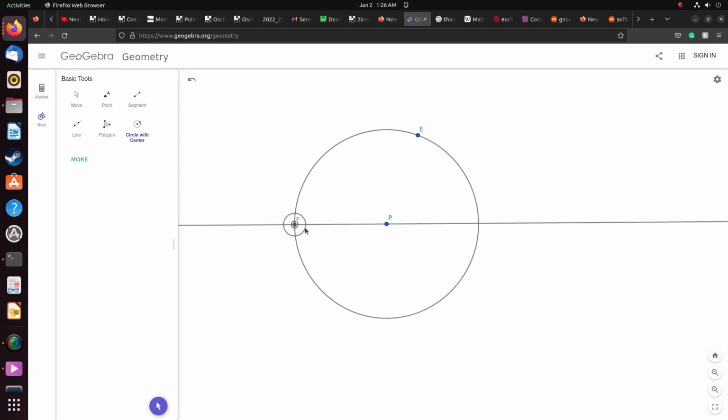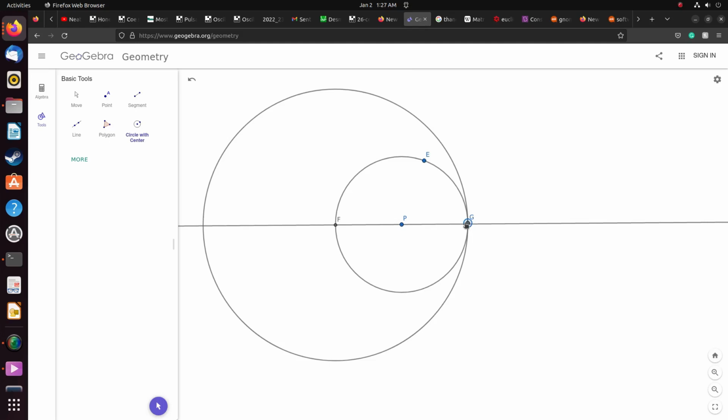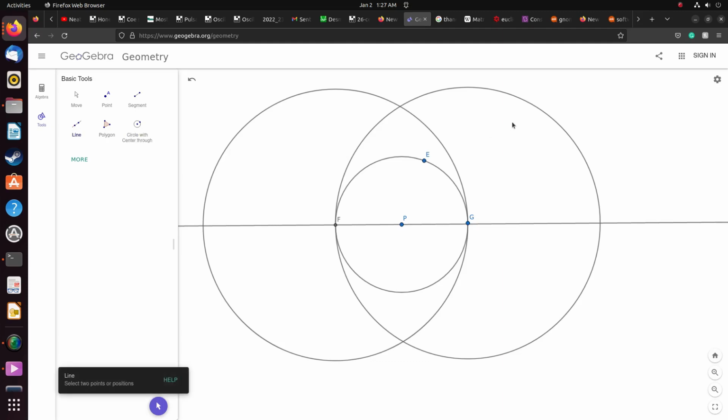So right here, you'd want the radius of these 2 circles to equal the diameter of circle P. So there, they would intersect the line in the same area that point P would. And you create another equal one at the other intersection. Also you want these 2 circles to be exactly the same. They should have the same diameter and they should both be on the same line.